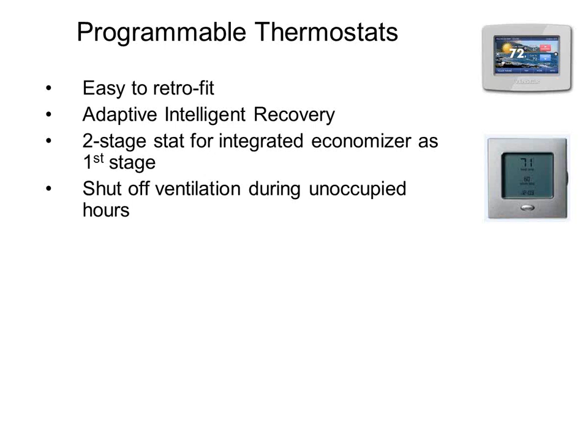On a normal package rooftop unit with a normal thermostat, programmable or non, when I go into the unoccupied mode at night, and then I get a call for heating or cooling to maintain my 65 or 80 degree setback temperatures we talked about, what do you think the fan does? Well, the fan has to turn on in order to run the heating and cooling, obviously.